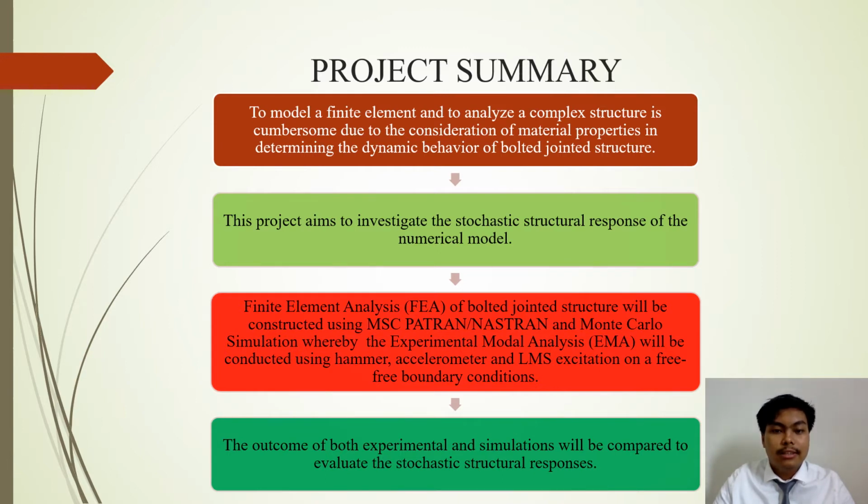Finite element analysis of bolted jointed structure will be constructed using MSC Patran-Nastran and Monte Carlo simulation, whereby the experimental modal analysis will be conducted using hammer, accelerometer, and LMS excitation on a free boundary condition. The outcome of both experimental and simulations will be compared to evaluate the stochastic structural response.